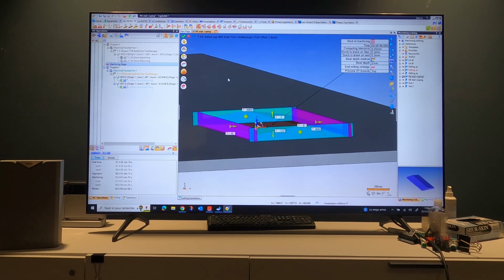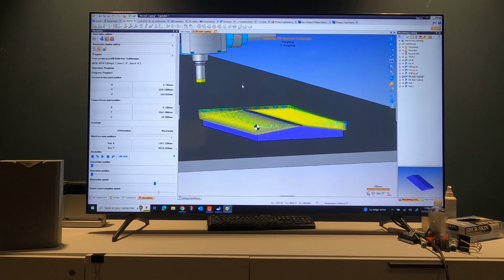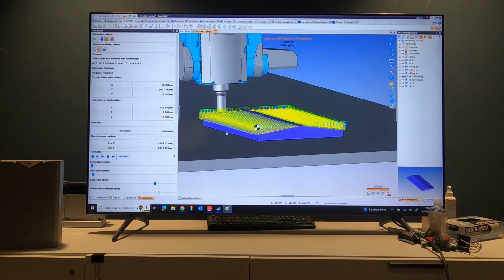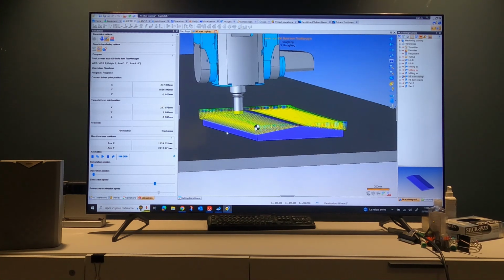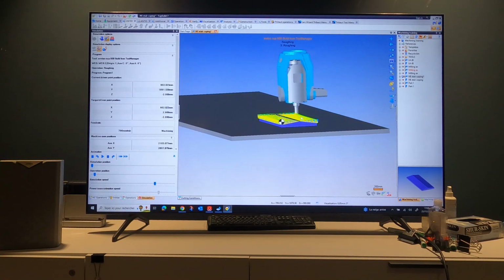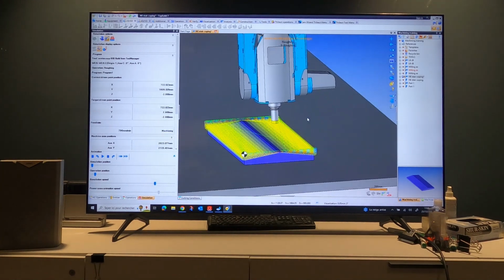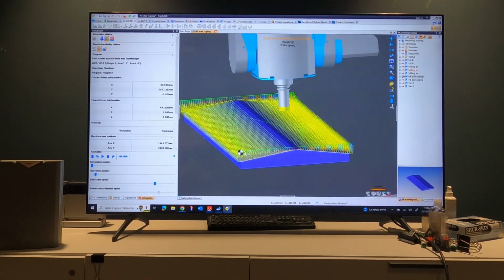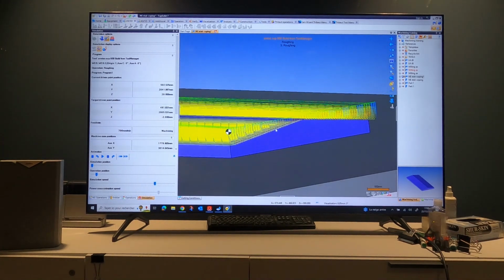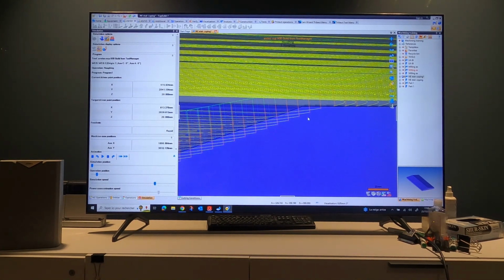Safety distance, under the geometry, should be just safety distance. So I have lean in, safety distance, lead out, safety distance, geometry right here. 20 mils? Yeah, that's when it's moving around the piece really fast. Oh, it has 20 mils of distance? No, it means don't come within 20 mils of the stone at that speed. Okay, 20 mil, I was saying the same thing but different.